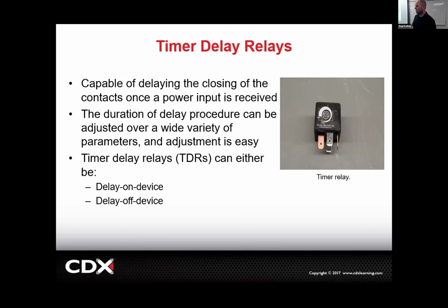Or I've even seen people add this to headlights. If you have to park far away from your house and you can't really see, you could turn your headlights off and then it will keep the headlights on for a certain amount of time. You could do this with a time delayed relay, but a lot of times the manufacturers catch on to that and they're like, we don't need a time delayed relay, we'll just write it into the computer to have the headlights stay on for 3 minutes so you can get your butt inside. Makes sense?